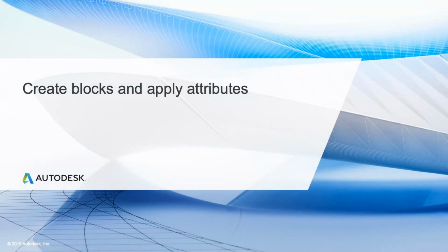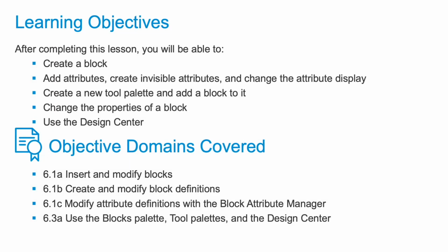In AutoCAD, a block is a collection of objects combined into a single named object. A block can be a realistic representation of an object or a simple symbol, like what is used in a schematic. Blocks could be stored locally or globally. In this example, we'll be creating global blocks, which are external files using attributes. Local blocks are available in the active drawing. You can use the Blocks palette to access blocks in other drawings to bring them into your current drawing.